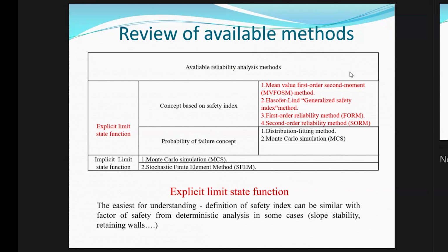Another is when we design for some loads, static or dynamic, we always make some assumptions. When you design this slab for people, for the operation load, we assume that this is like 5 kilonewtons per square meter. This is some kind of approximation.